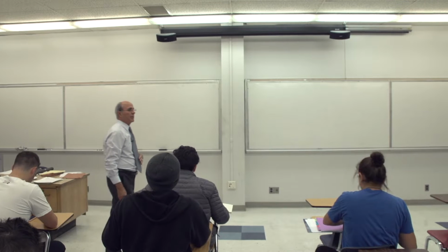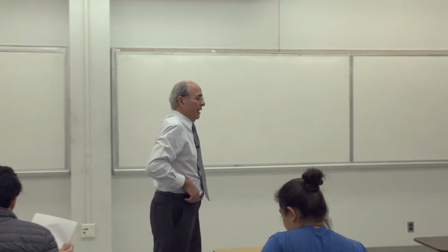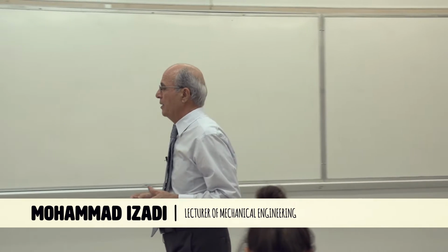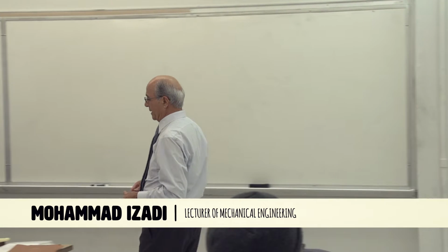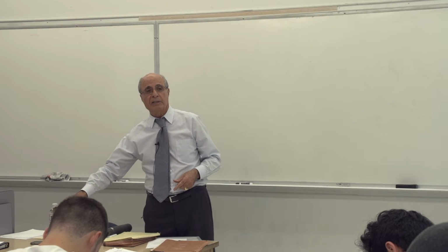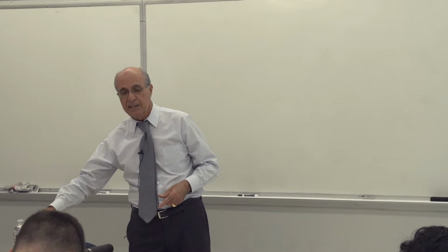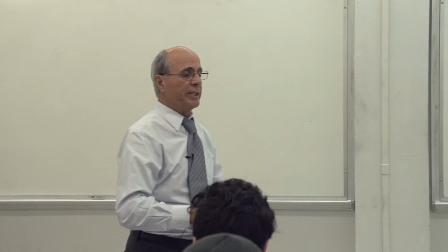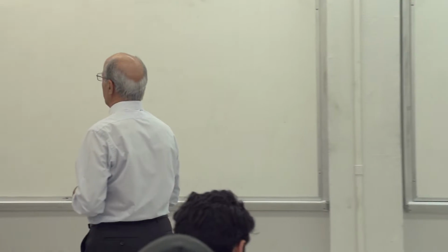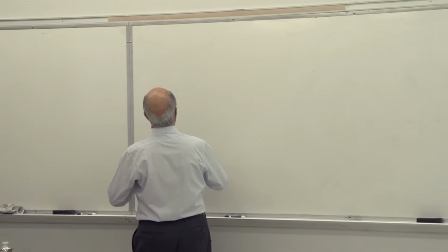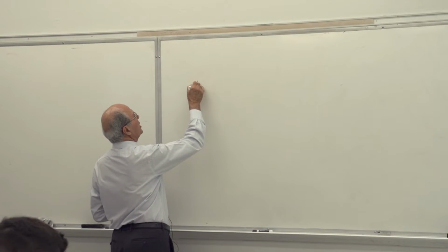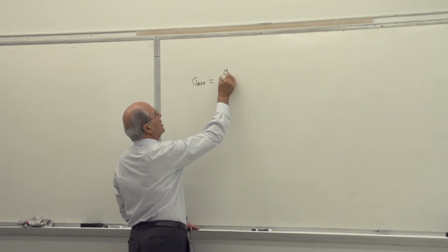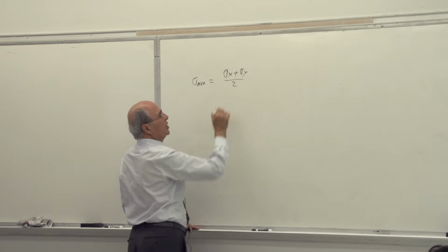Idea behind the Mohr circle, because what we did last time, we ended up with the equation for the circle. Remember what happened at the end? The discussion was that those three equations, 7.5, 7.6, and 7.7, when we turned them around, maneuvered, squared them and added them together, we'd end up with a circle which has the following characteristic. First of all, the center of the circle is the sigma average. We decided on that one last time. Remember that? Yes, sigma average was sigma x plus sigma y divided by 2.